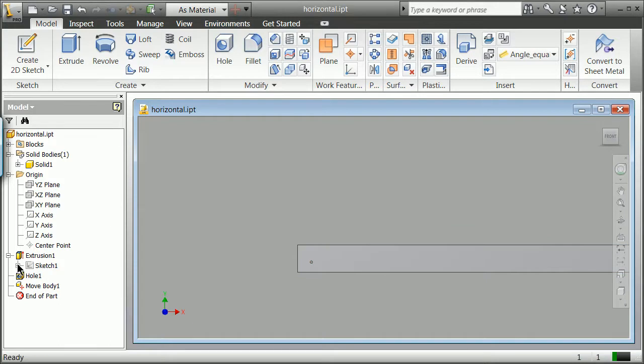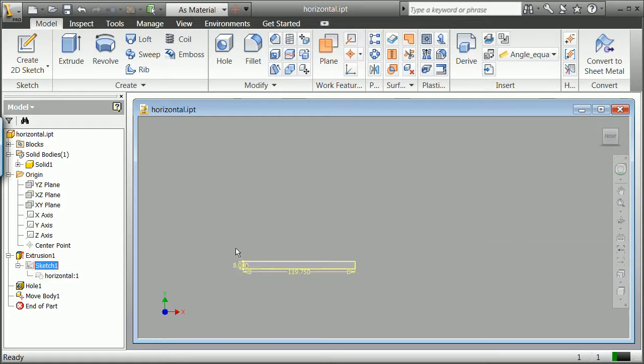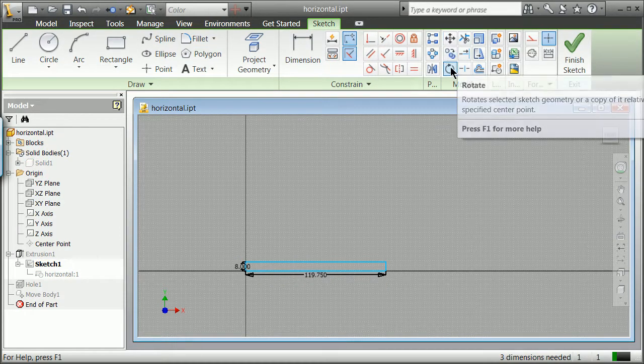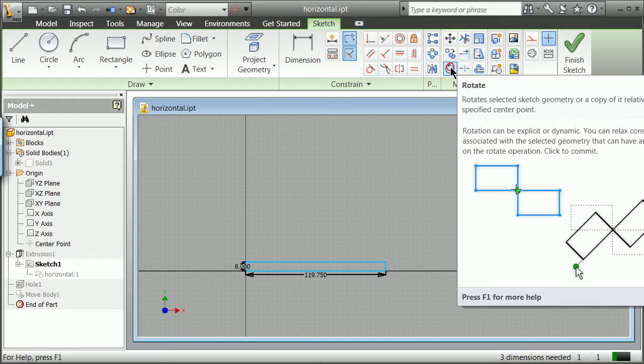So remember, of course, we started by bringing in a sketch block, but we can go into here, right, and we have this piece, and we can click within there, and now we can do, if we need to, we could move. I'm sorry, you have to double click within the sketch block. Once you get to the sketch, now you have some ability. You can see it's context driven. You can do a couple of things. You could rotate, you know, and we can rotate, right?